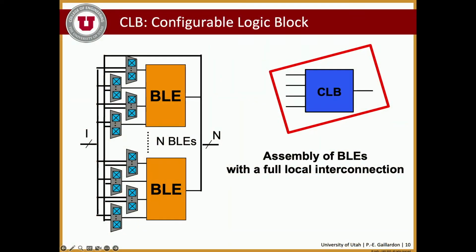So now moving to this CLB block, right? We have some level of routing, but that won't scale very far, right? Typically, N will be equal to 10, between 8 and 10. This is what you'll find in commercial FPGAs, for the number of logic elements that you put together inside of a logic block, whether it's called a LAB in Intel and Altera's technology, or logic elements in Xilinx, AMD.